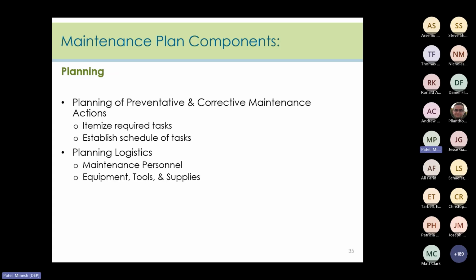The second essential element is planning, which paints a complete picture of what should be done by maintenance personnel. We would not want someone to say, for example, mow a bioretention system with a meadow, thinking it was an overgrown detention basin. Planning includes the schedule of tasks, the tools that are needed for each task, access information, where sediment or trash is to be taken, and if it requires dewatering, where that is going to occur. If there is an internal component and it is destroyed by a large storm, maintenance staff should be able to correctly repair or replace it.